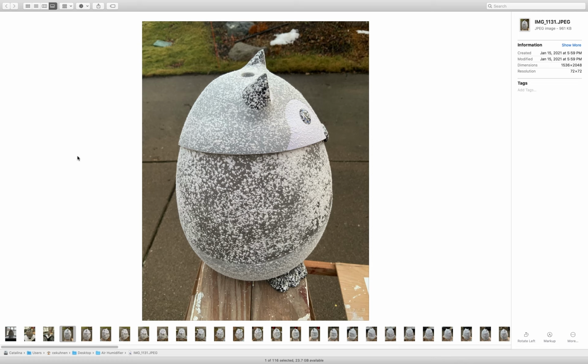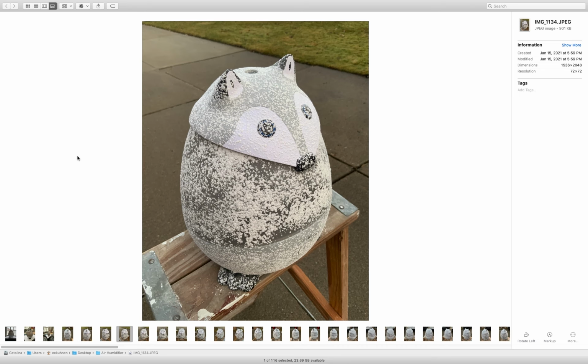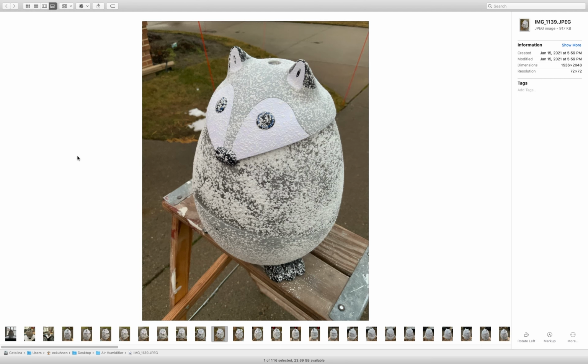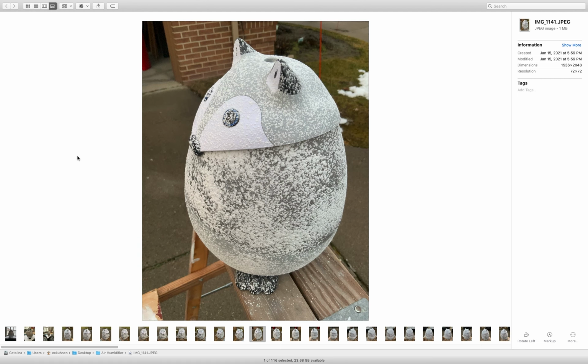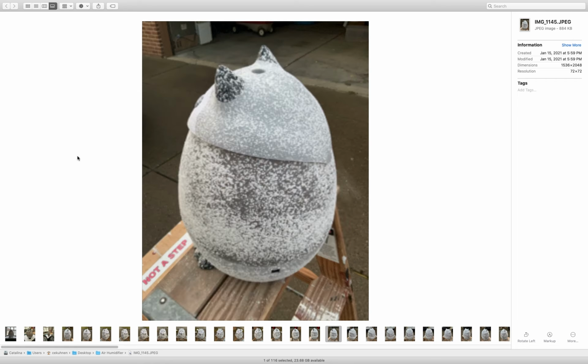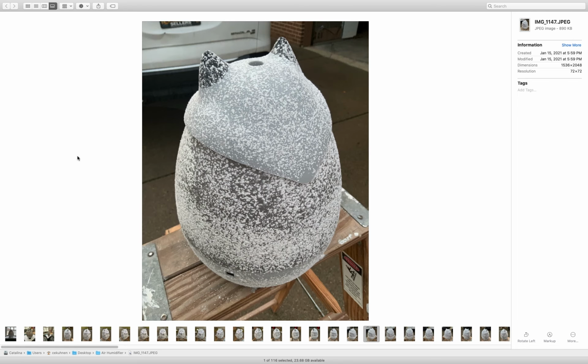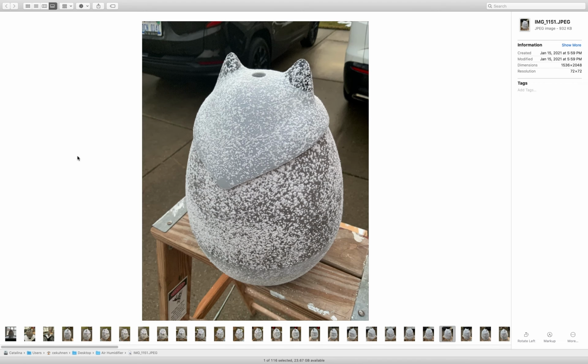And the good news is, it is actually a very easy process. All we need is an object, a camera. In my case, I used an iPad Pro. And we have then to create a sequential set of images. You see that I tried to frame as much of the object as possible. And I go step by step and then take a photo. This helps overlapping the object from frame to frame.